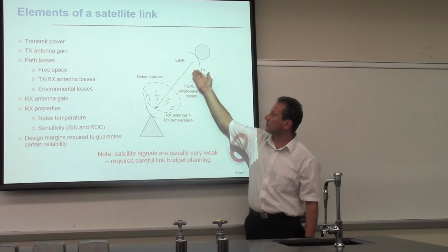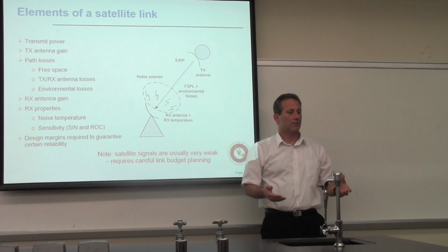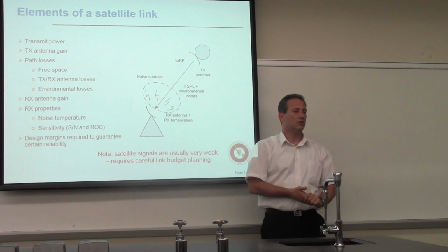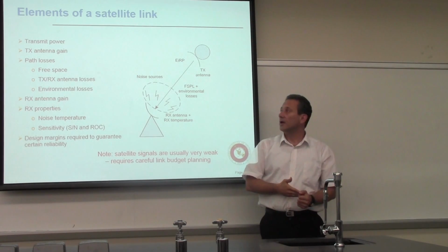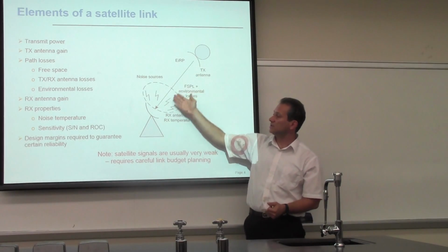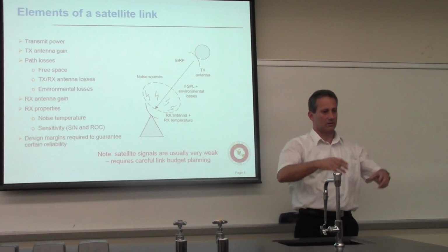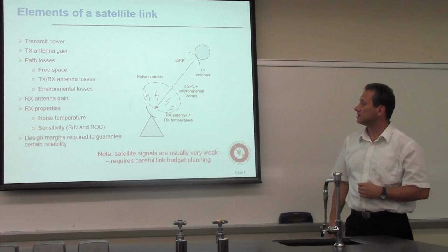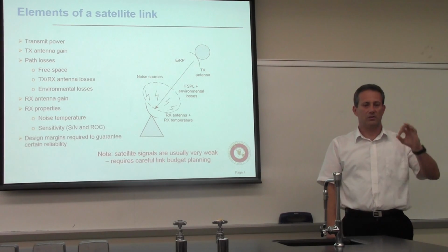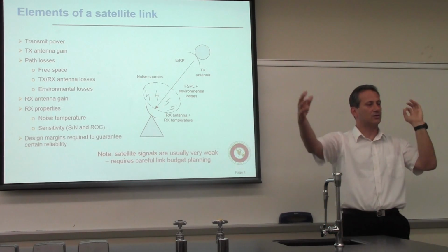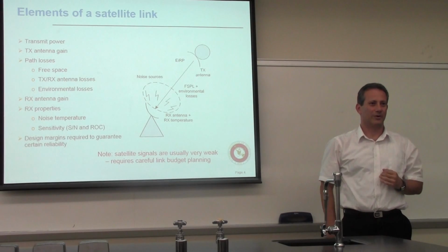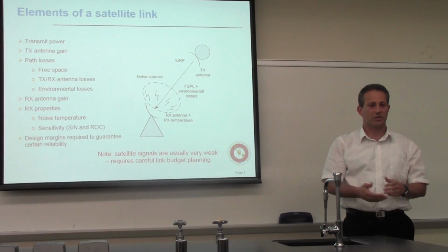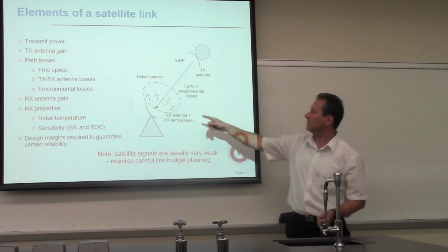The signal that is coming from the satellite needs to be received by the Earth station. But depending on what is within the main beam of that Earth station, you may have a certain amount of noise. And luckily enough, this weak signal here is usually against the sky, which, if your antenna has a relatively narrow beam, means you see a small, tiny portion of the sky. Unless you have the sun coming through the main beam of the antenna, you're actually working against much smaller noise temperature than the other way around.